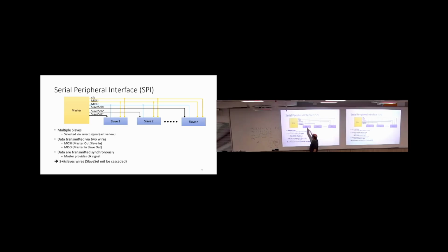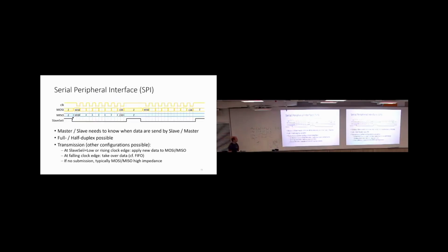One to communicate from master system to the slave. One to communicate from the slave system to the master. And then on this master server side, you have also a select signal where I can say, I want to talk with this, this, or that. And then I can run effectively simply on top of this system some specified protocol, which is: my clock is pulled to high as long as I do not want to send.